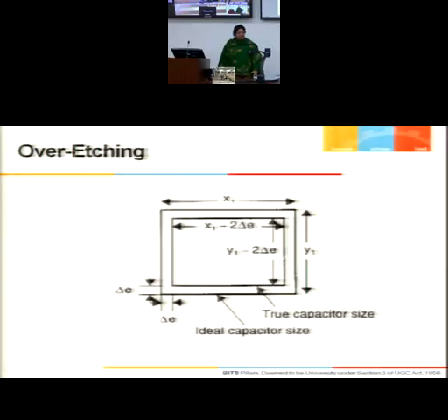I intend to create 20 micrometer, but because of over-etching I am getting 18 micrometer. Maybe 1 micrometer is too large; normally that delta E is going to be very small, but it nonetheless exists, it is not 0. But let me just take a value. So 18 micrometer and 10 micrometer will become 8 micrometer.